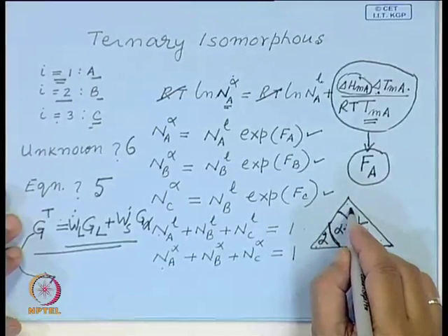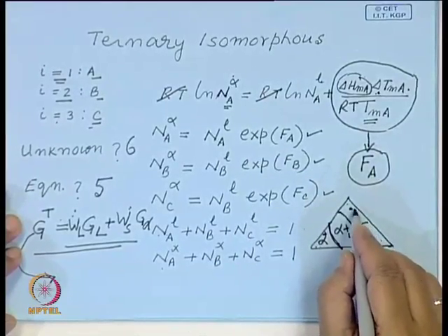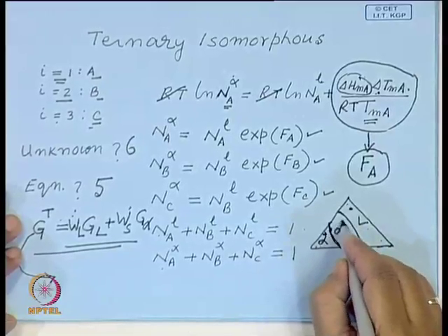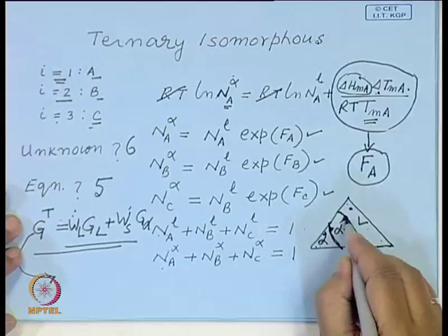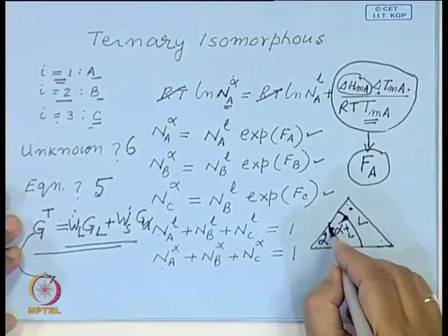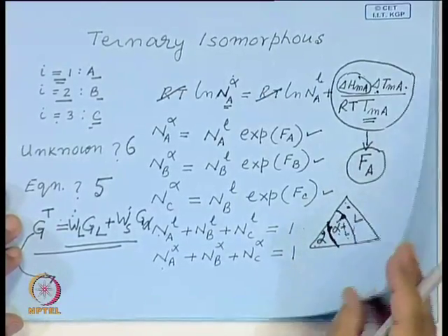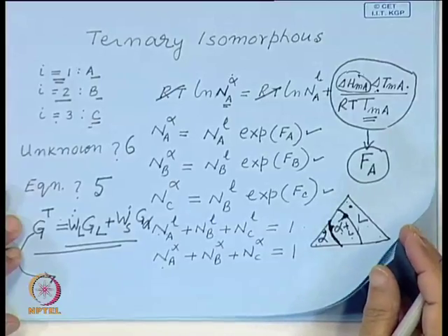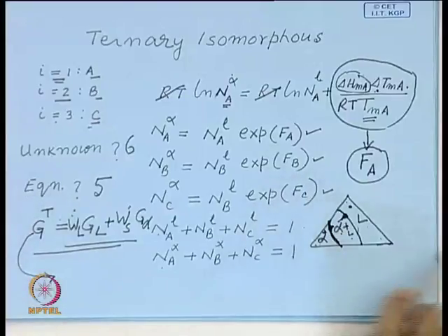Here you find that only if it is 100% liquid, the free energy is minimum, but in between it will vary, and similarly you will be able to find out where both can coexist. In that case you can construct this boundary. So this is how the computation of a phase equilibria problem is solved in a higher order space.